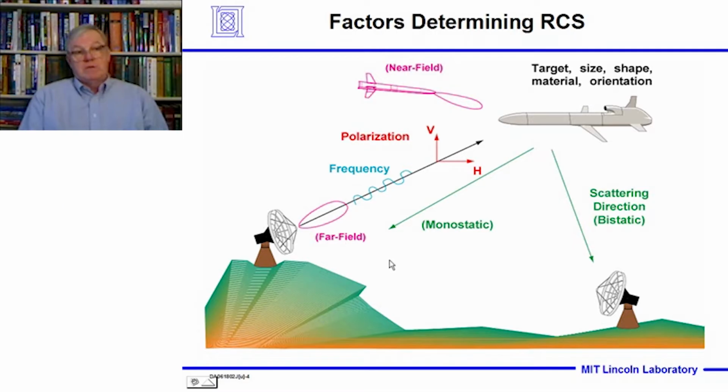So you're going to have to put in both of these orientations, both of these locations relative to the orientation of the target, and therefore the bistatic cross-section data would be a lot bigger. There wouldn't be just a cross-section number when you're located here, looking nose on. There'd be a cross-section number when you're looking nose on, and different sets of angles off the side. It's another whole parameter you'd have to worry about.